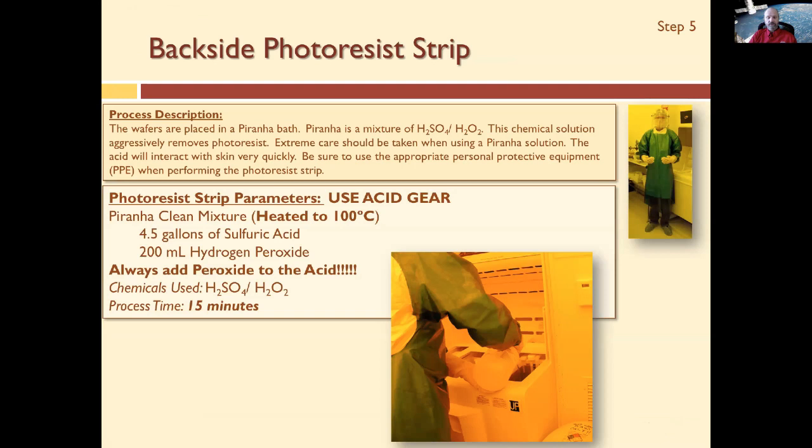So we can actually do it in a bath and do a bulk etch or a bulk strip, or you can do it in beakers. Okay, so you can imagine sulfuric acid and hydrogen peroxide, they will chew up organics really well, and they strip a lot of things like metals, trace metals, and that kind of thing off of the surface. So it really cleans the surface well, and we typically do it at high temperature. High temperature makes chemical reactions go much faster.